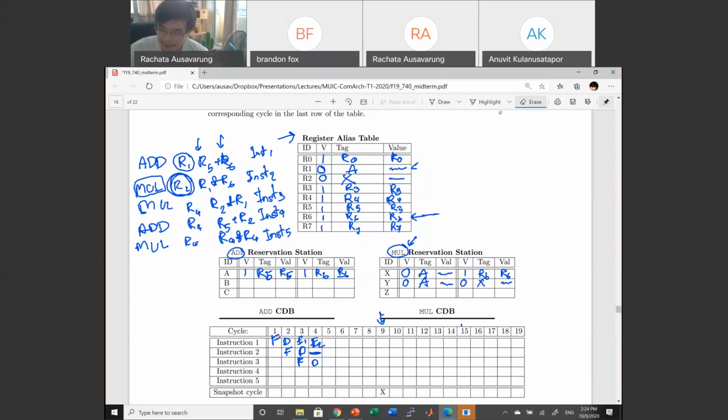All right. Awesome. And then what do we have to update in the register aliasing table? You are modifying R4, right? So you go to R4. R4 is no longer valid, right? The valid bit becomes 0. What is the tag for R4? The tag becomes Y, right? And this is not known. That's it for cycle, oh, and I forgot to fetch. That's it for cycle number 4.